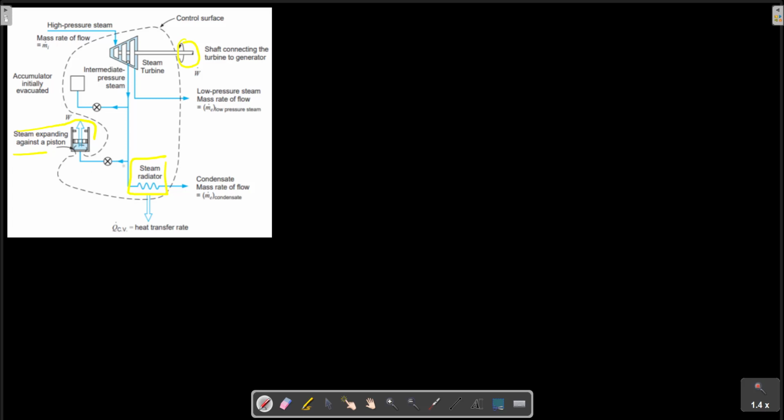There is a mass flow here, and a mass flow here, and also a mass flow to the turbine. It is important to identify and label each flow of mass and energy and the part of the control volume that can store mass accumulation.